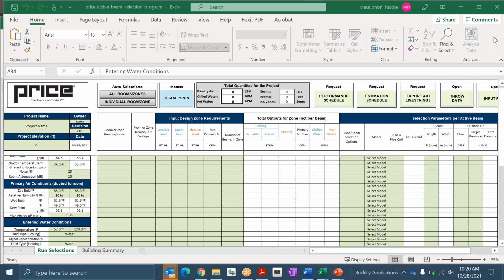And then once you make your selections, you may want to consider dropping your static pressure levels down, looking at the overall selections that you have, to make your selections that much more accurate or robust. So again, don't get caught up in that static pressure piece. Pick a number to start with, and then dial it in as we start making our selections.